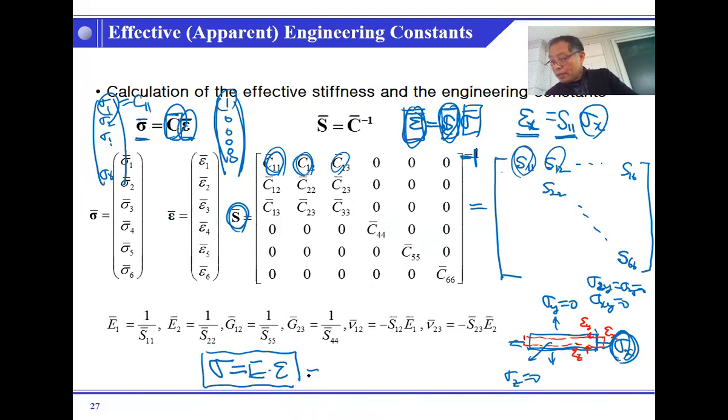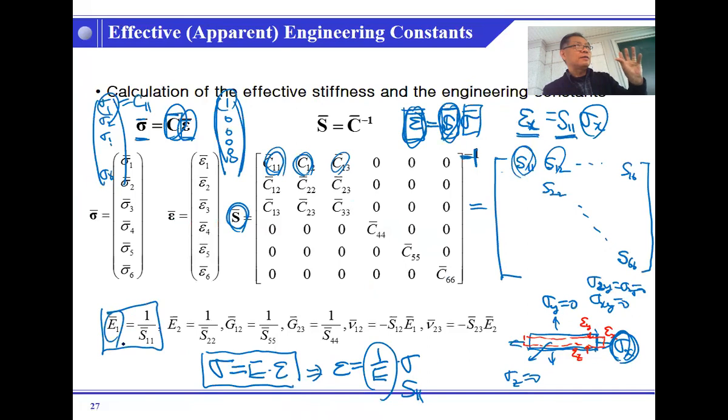So that's why we can say this is the strain and stress relation, and this is S11. Okay, so we are measuring epsilon 1 from experiment, and simply we are measuring compliance. All the compliance directly from material property, engineering constant.